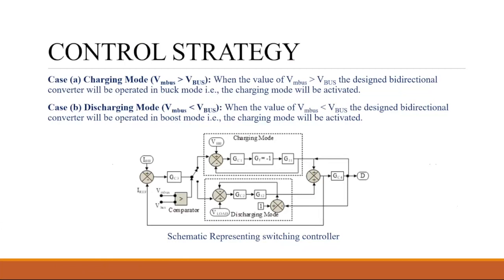All we are doing here is taking the reference. There's a reference bus voltage that we have set, and we are taking the feedback of the voltage again and again, and we are seeing if the measured bus voltage is greater than this value, then the logic will be 1. If it is 1, charging I have to do. And if it is less, the logic will be 0. Discharging I have to do. That's it. It's easy.